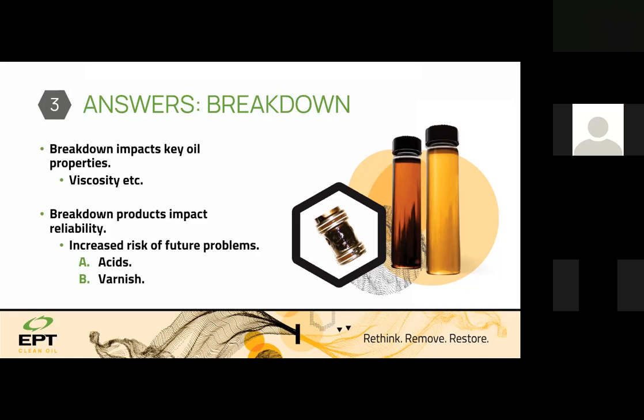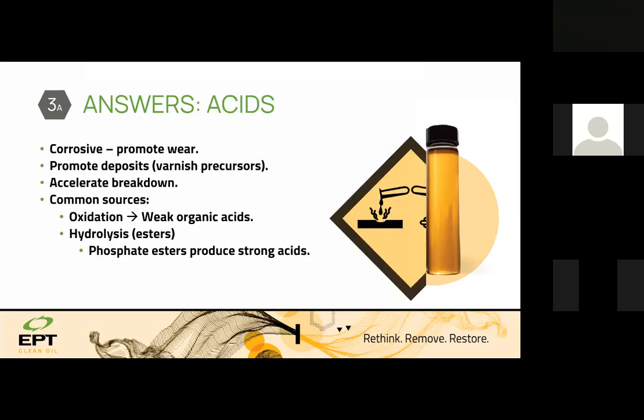The most important test historically has been acid number, and then today oxidation byproducts, where they accumulate in the lubricant, and then we can test for how much it is accumulated, how much the lubricant is keeping them inside, how much it is saturated from those oxidation products. We can test for it today, and the end of the life of the lubricant also can be tested.